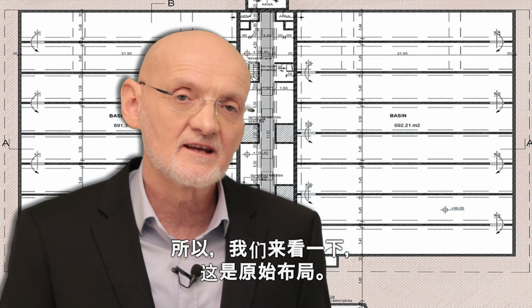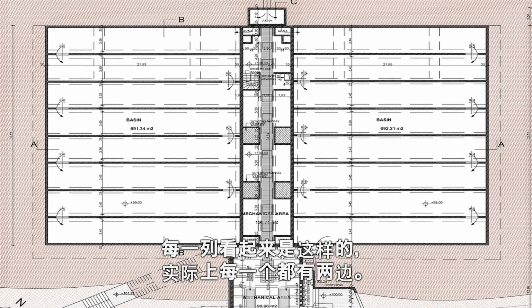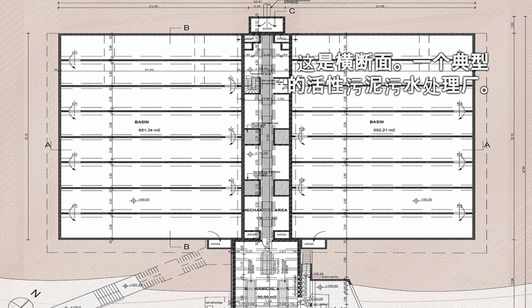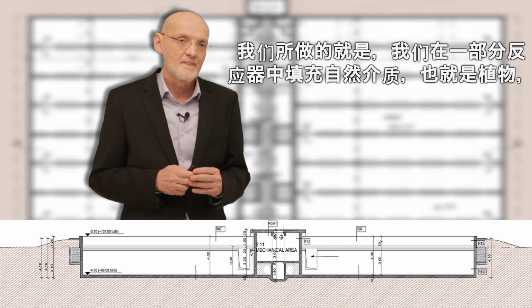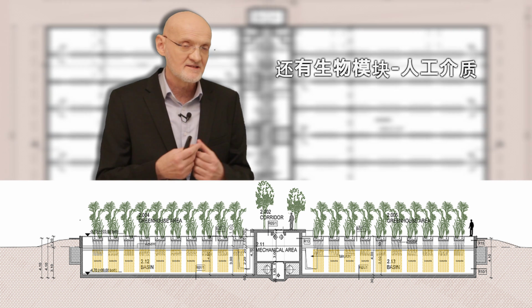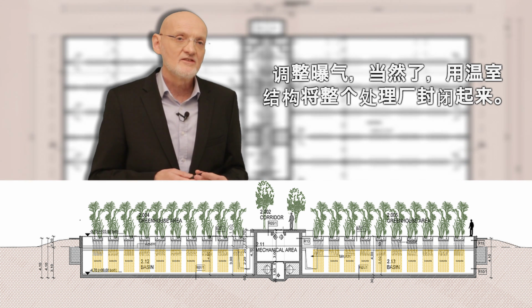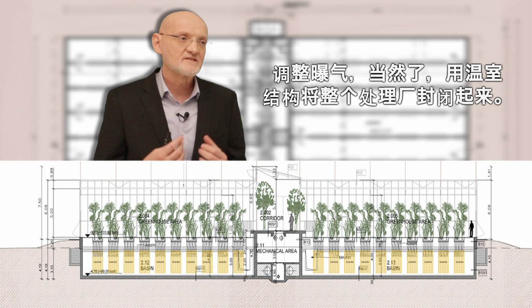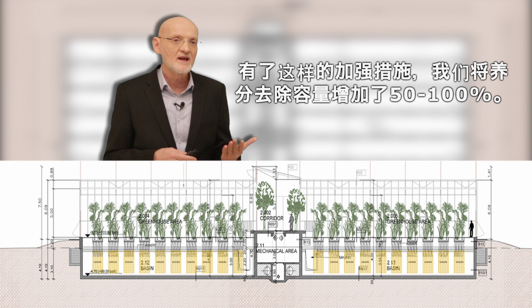So let's take a look at this, this was the original layout. Each of the 3 trains looked like this, which actually has 2 sides to each. And this is the cross-section, a typical activated sludge plant. And what we did, we filled the reactors partially with natural media, which is the plants, and also with biomodules, the artificial media, adjusted the aeration, and of course, enclosed the entire plant with the greenhouse. With this kind of intensification, we were able to increase the nutrient removal capacity by 50 to 100%.